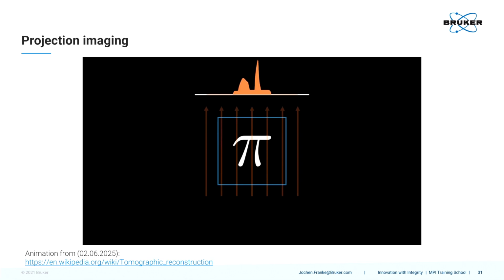Now what we can do is back projection of the acquired projections to receive our image again. Now this is a bit blurry, that's why we can do a high pass filtering beforehand and do the filtered back projection in order to have a more crystal clear image. Clear so far? Thanks.